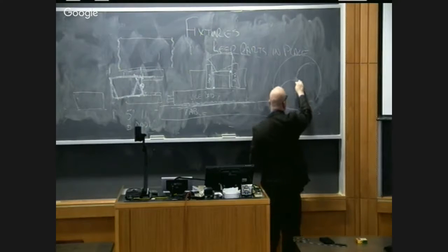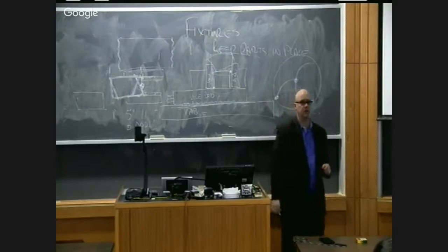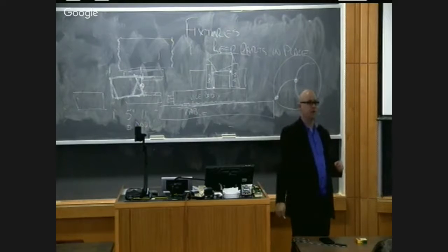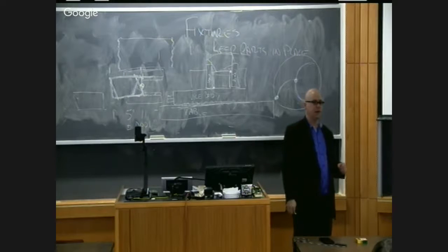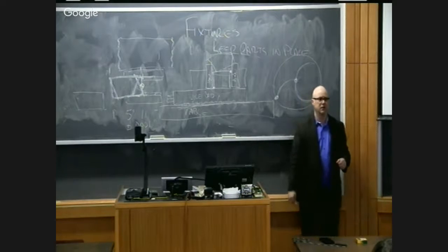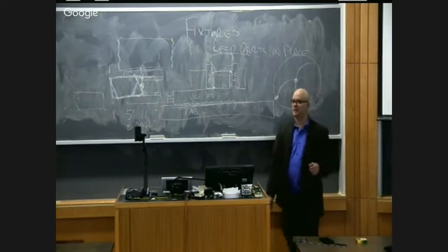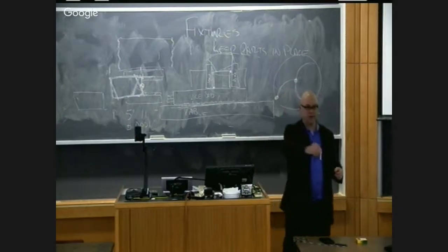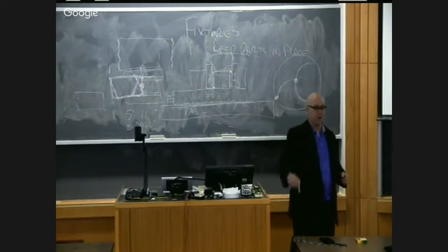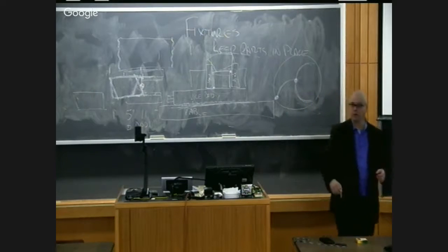But the surface speed here is 0. And as you get closer and closer to the center, it approaches 0. So it's not cutting anymore, right? If there's no surface speed, it can't cut. What does it do though? Because it feeds in, it's got to sort of mush the material out of the way. It's got to form the material instead of cutting. Don't worry, it can form the material because there's plenty of heat, right up until the end mill goes explode. So that's why we have you ramp in or spiral in if you have to come into an area, or you can drill a hole.